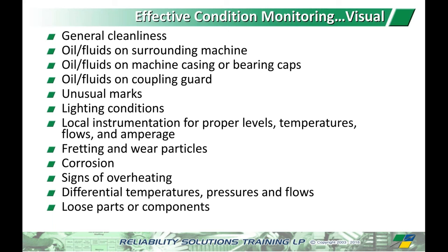Local instrumentation, of course, and as I said earlier in this presentation, one of the things that we are very, very weak at is providing good instrumentation to allow us to assess the performance of our machine. And this doesn't mean I've got to put gauges everywhere, because as soon as you put gauges everywhere, now you've got to maintain those gauges and they get covered in dirt and broken and busted and everything else. But at least have the pressure ports to be able to install a gauge.